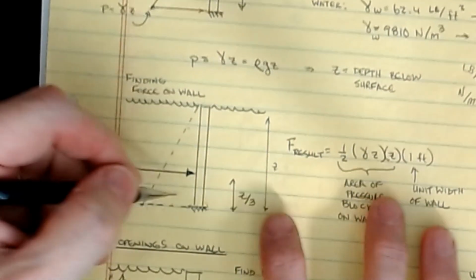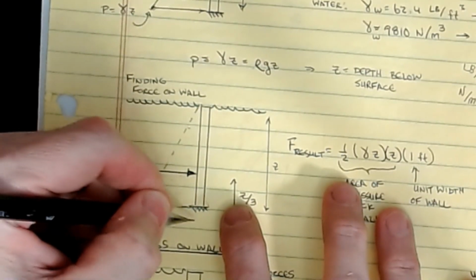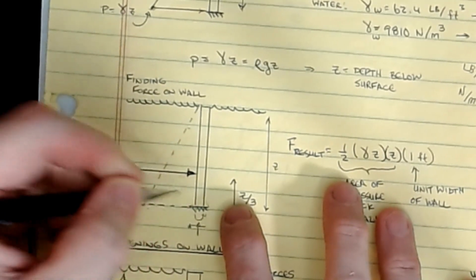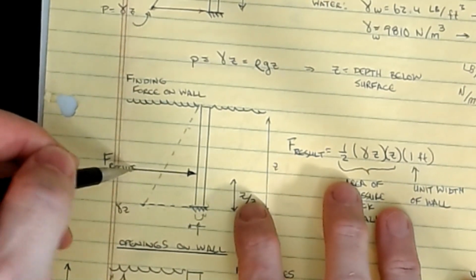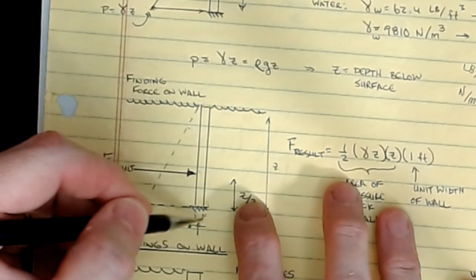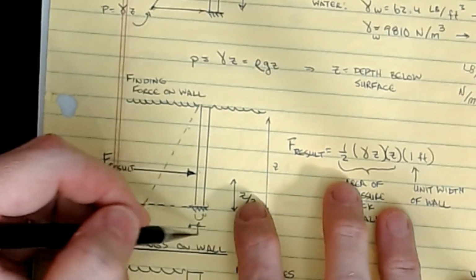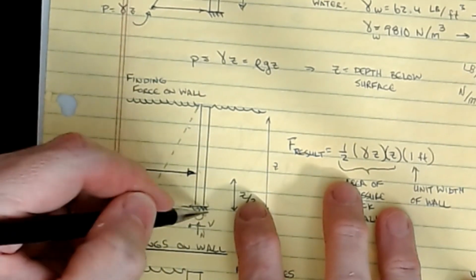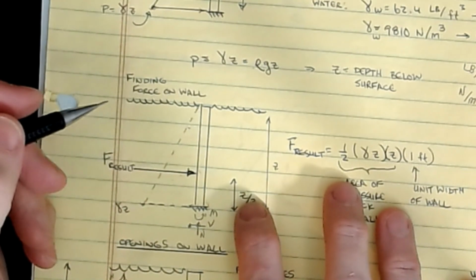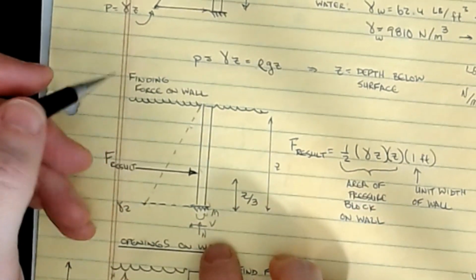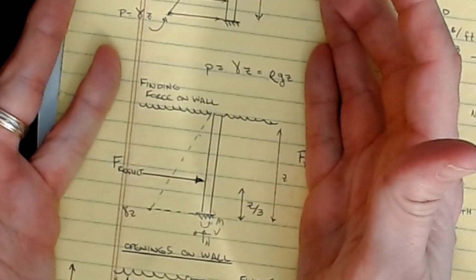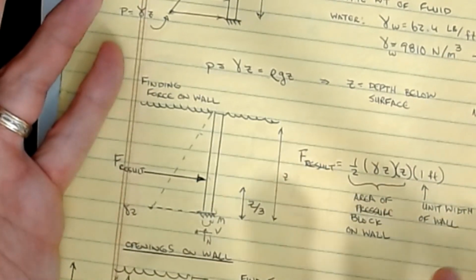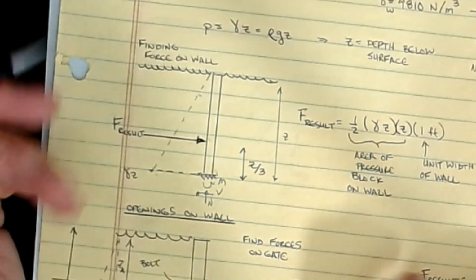Okay, I could come in and say, well, this is my wall. It's fixed at the bottom, and so maybe there's a moment, and maybe there's some horizontal shear and a vertical. With this load acting on this wall, I could tell you what the support reactions are. What does the shear, that's this guy, the horizontal, what's the normal, and then what's the applied moment that has to happen on that as well. So that's the case, and we're back to doing exactly what we did in the last video with forces, finding centroids of forces, and then using that to find support reactions and those kinds of things.